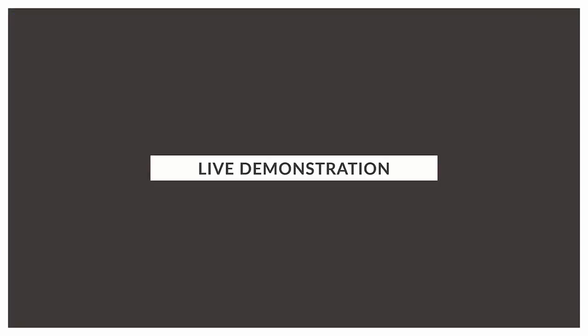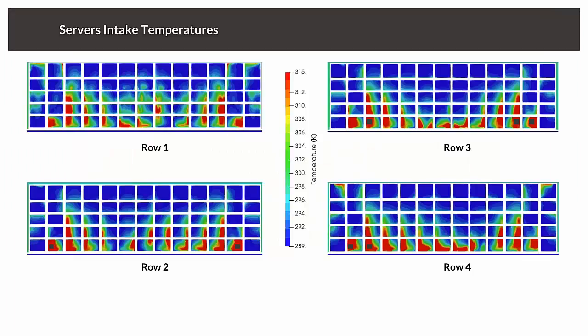Since we don't have much time, I'll move to the next section, the results summary, and what we actually obtained by running all these 16 simulations. Let's first take a look at some results. Since we have a limited amount of time and we had 16 cases, I'll focus on a single simulation that was running at 120% of the flow rate capacity and 16 degrees centigrade inserted into the bottom plenum through CRAC units.